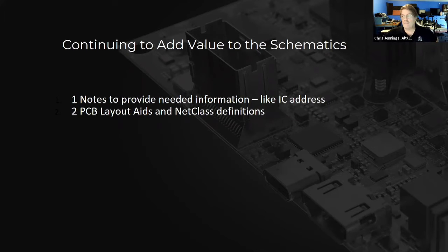And all of the power in that device, now I have probably 100 times that capability on my phone at this point. So that's why voltages continue to reduce. That's why we continue to put more and more into ICs. And the impact of that is higher frequencies on PC boards, which affects layout.